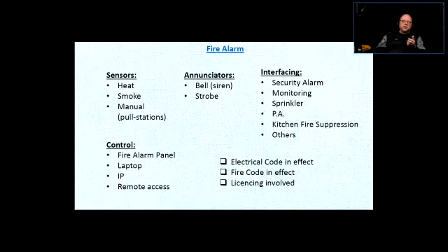And the speaker is basically for the purpose of announcing, look, this is a false alarm, or this is a drill, or this is not a drill, please get out of the building now. And that would trigger all kinds of procedures involving people who are responsible for getting people out of the building. So the PA systems do work together with the fire alarms.